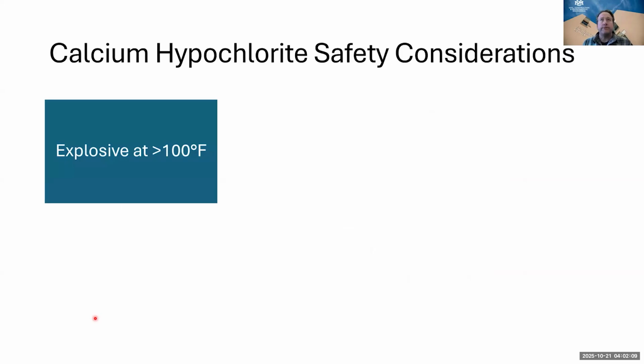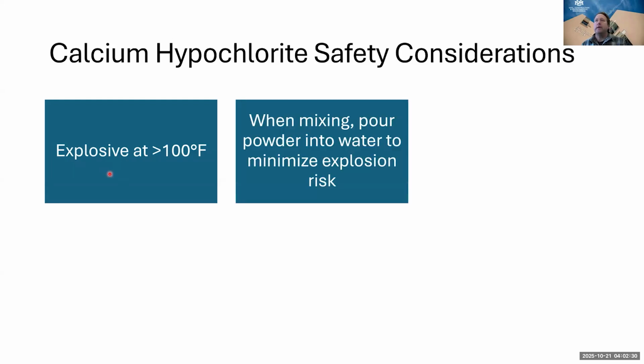So some specific safety considerations you should take when we deal with powdered chlorine or tablet chlorine. It really needs to be stored in cooler conditions. If it reaches temperatures greater than 100 degrees Fahrenheit, it can become explosive if there's certain aggravating conditions.